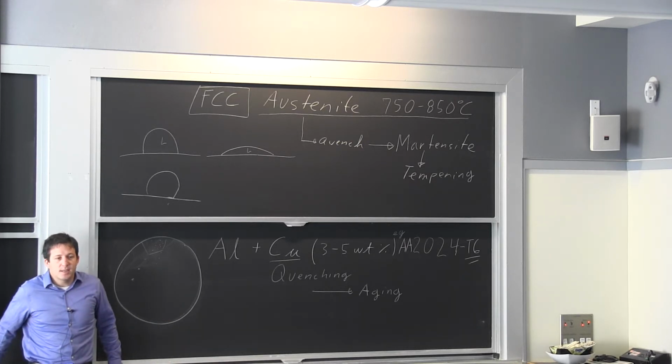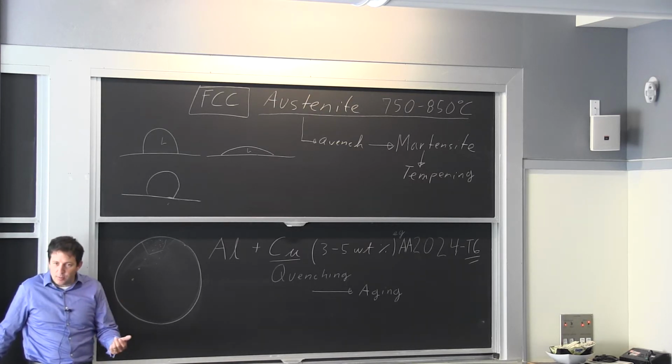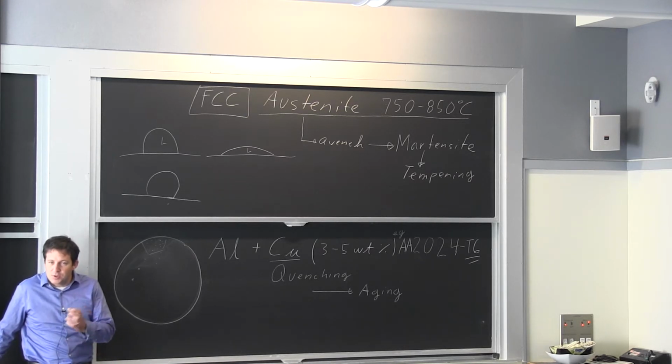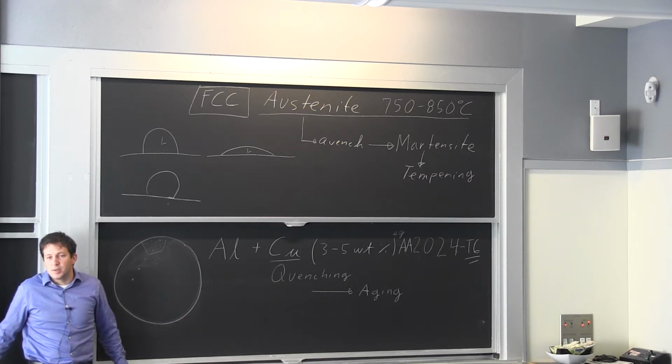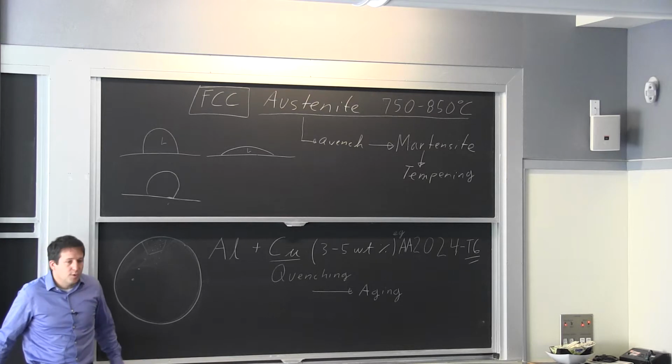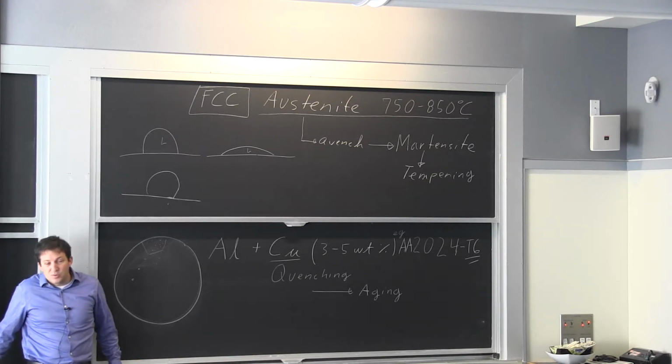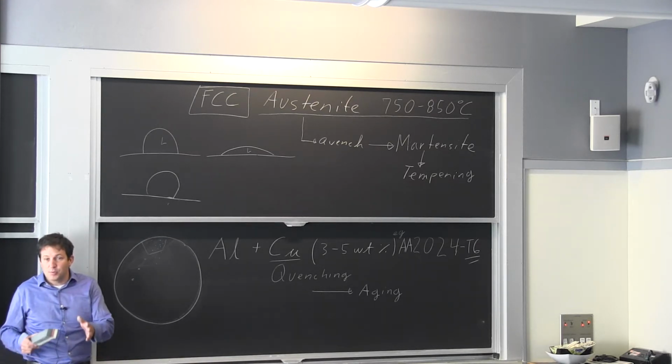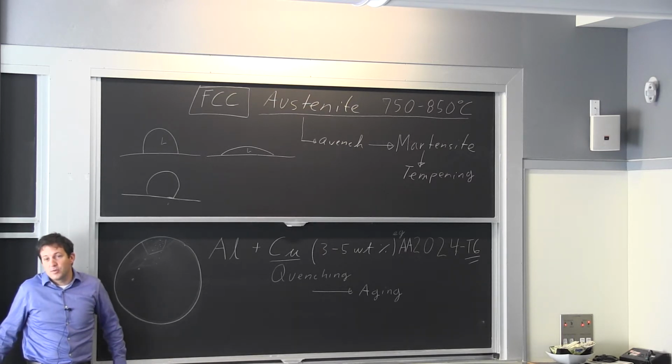So any process that happens at a very high driving force, that's what we're trying to do. We're increasing the driving force, and we're reducing the growth rate. So it nucleates quickly, it takes time to grow, you get many. That's pretty much the bottom line. If you were closer to the equilibrium temperature, the driving force to form them is very small, so when they form, they're going to have to be really big, and they're going to continue to grow very quickly because of the diffusion. It's a good question. Thank you.